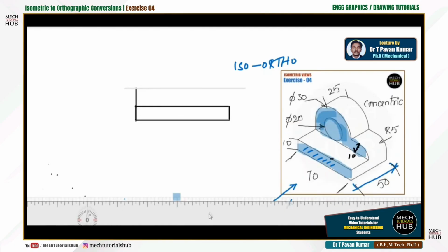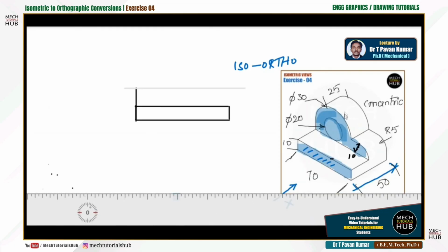This locus will help you to draw a circle with the help of a compass. Now the outer diameter is 30 mm, so I'll consider radius as 15. From this line I'll measure 15 distance to figure out the midpoint of it, somewhere maybe here. So let me draw a circle. As I am not drawing it conventionally, let me draw with my free hand. Somehow I have managed a diameter of 30, radius of 15, by considering this as the center. With the same center, again one more diameter is here, which is of 20 dia.